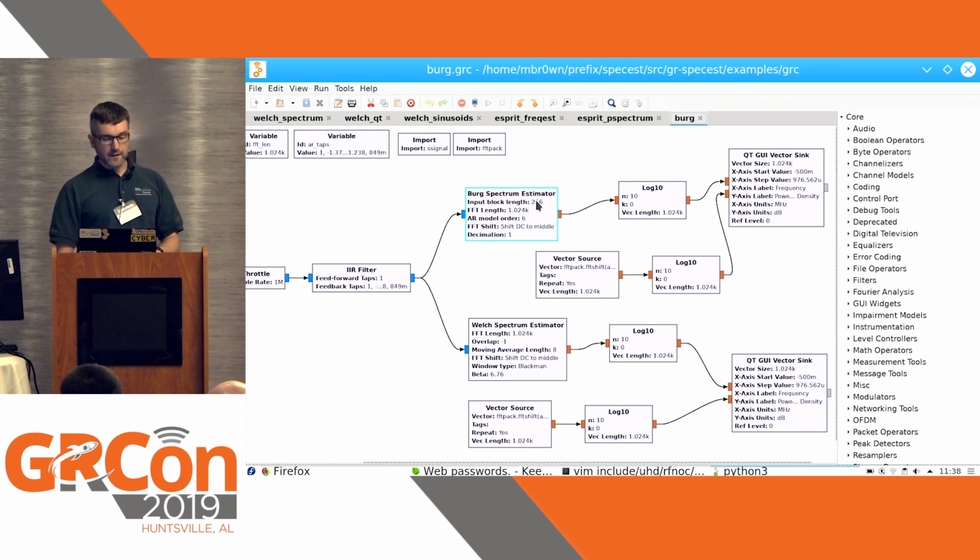And here, I will give a little bit of a clue what's going on by telling it the model order. I'm going to say, you're supposed to try and figure out what this filter was, and its model order, the number of coefficients in its polynomial, does not exceed 6. That's it. You go figure it out. And then this will produce a pseudo-spectrum of its own. Okay, let's run this.